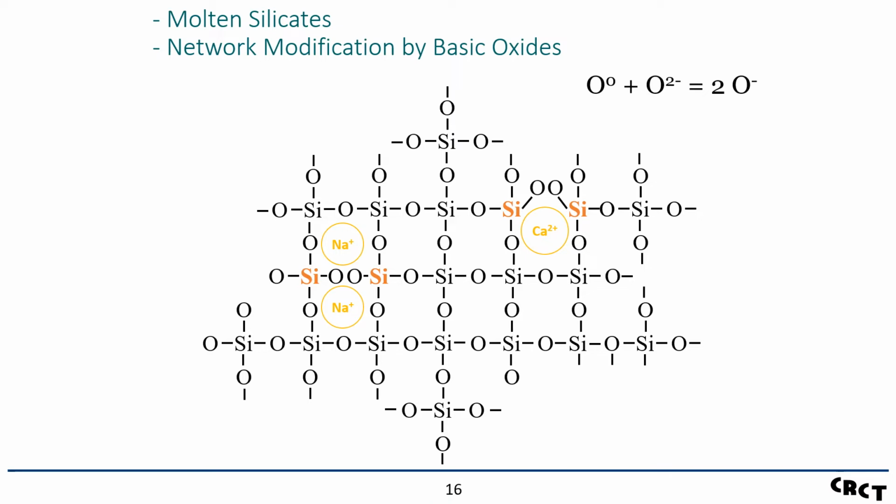And we've done this now, as I said, for a large number of basic oxide solutions. Now, when we come to molten silicates, we've jumped to far more complex solutions than just a random mixture of cations. As you know, we have a network. Let's take a molten silicate containing silicon oxide and, say, calcium and sodium oxide. As you know, there's a network of silicons bonded through oxygen bridges to 4 neighboring silicons. This is called the silicon network. This is a two-dimensional representation. These, of course, are really tetrahedral coordination.